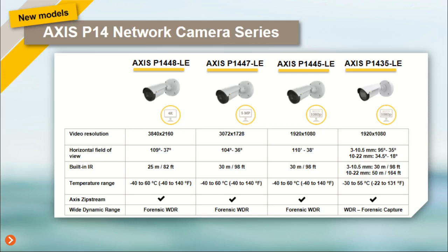And I see the H.265 part. No, it's not supported at this point. We have some cameras with H.265. However, honestly, at this point we see that there are still a lot of questions around H.265, also on the licensing model and on the decoding side. Our cameras can do it, but then there's no PC in the world which can view the pictures, for example. So there are some challenges in this world. On that part, we don't fully believe in H.265 yet.